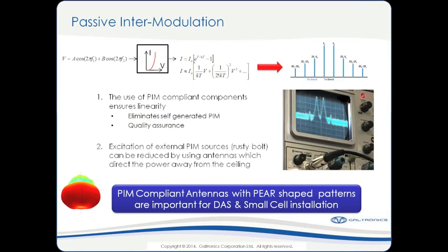What's shown here is that if you look at the diode equation, the exponential term can be replaced by a Taylor series expansion, in which case you start to see the squared terms. And if you remember your trigonometry identities, squares of cosines generate plus and minus angle products, and create this spectrum that's non-ideal. So that's the math at the top, and the figure at the right shows a practical measurement of it.